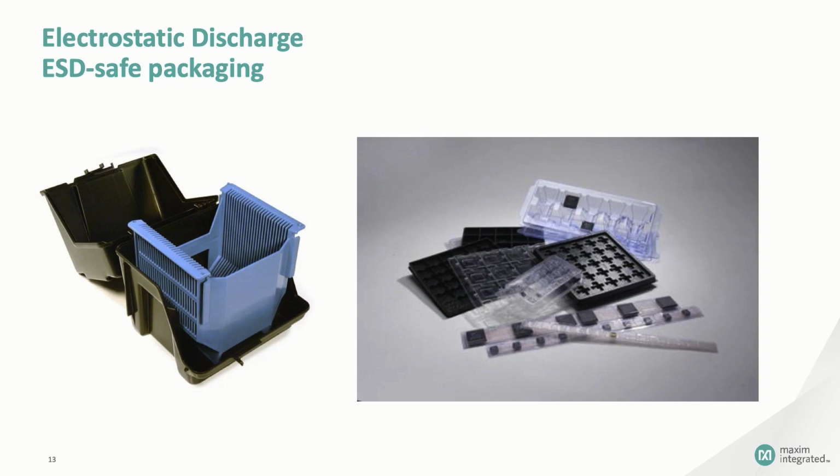When we deliver parts to customers, we provide them in packaging that is static dissipative. That ensures the parts will arrive in the same excellent condition as when they left our factories. Now, one note about packing material. There is anti-static material, and then there is static dissipative material, and they're not the same. Anti-static material won't accumulate a static charge, but it doesn't protect the contents from a static discharge.